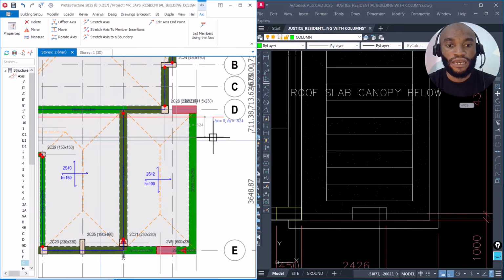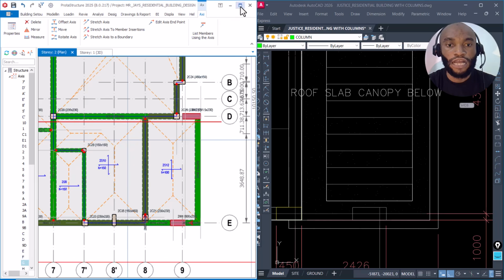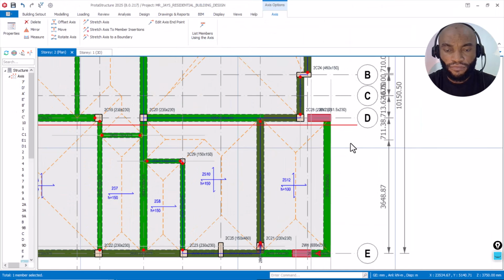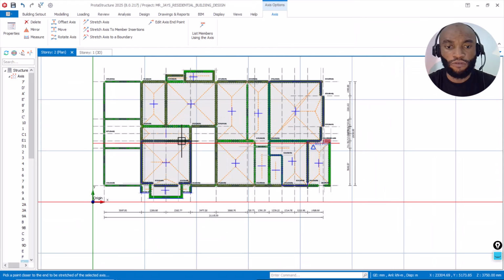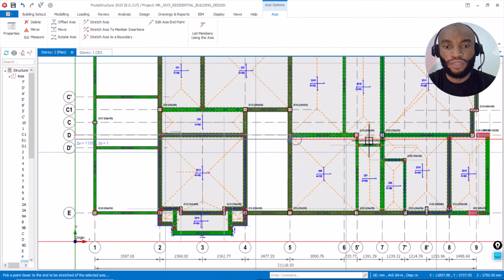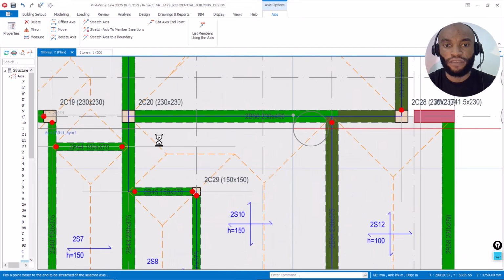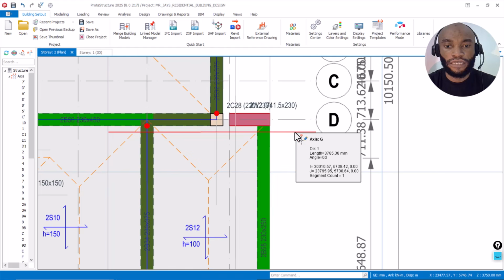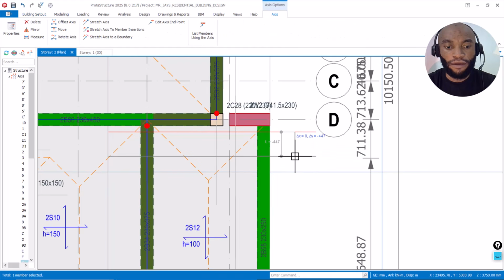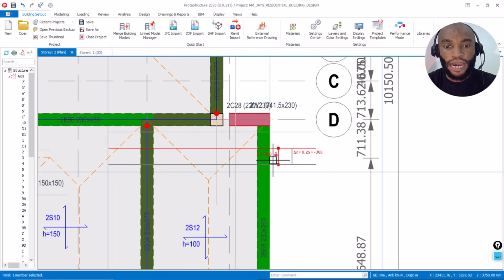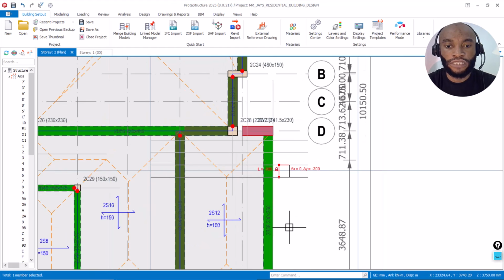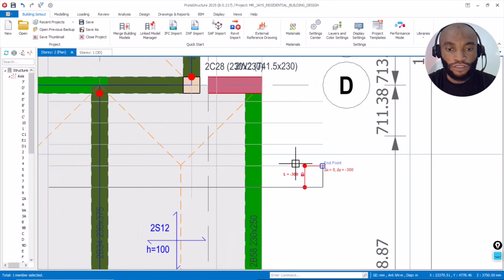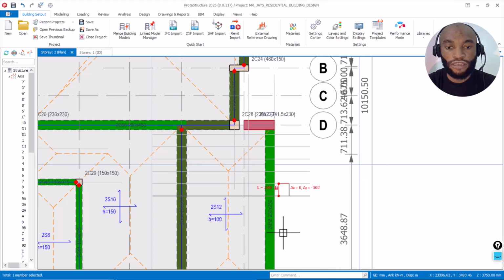Knowing that now, I can come back and maximize this automatically. That's fine. I can choose to stretch my axis backwards since I don't want it to be bigger than this length. Stretch it backward like this, and then keep this here. Okay, that's fine. So I click here and then say offset, and I use the F2 key and type minus 300 since I'm going downward, and I press Enter. Then I'll just continue clicking, because it has already locked that dimension offset value to 300. So I'll just be clicking forward, and we'll be going down till it gets to the final place. Okay, that is fine.